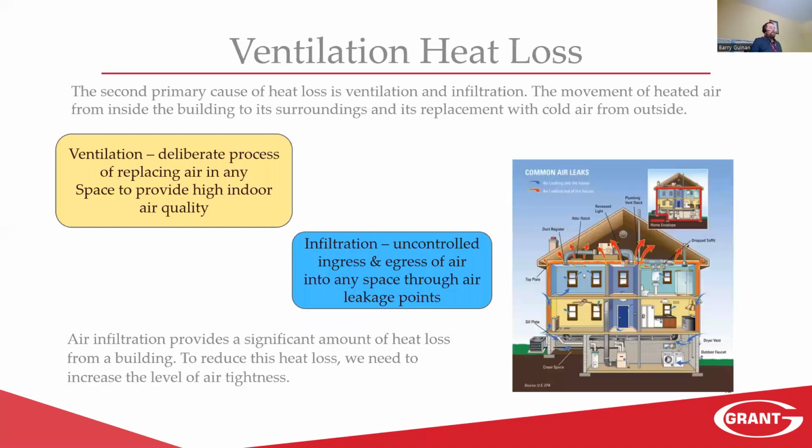The second part when calculating heat loss is ventilation heat loss. There are two primary causes of this: ventilation and infiltration. It is the movement of the heated air within a space, transferring from inside to outside, lost to the surroundings, and then being replenished with cold air.